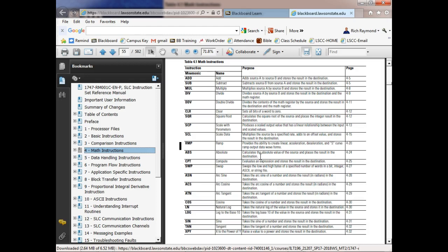And then it's just like robots. So robots, they got tons of instructions they can put into a robot computer, but why would I need the welding instructions that would eat up memory that I'm going to use for my program if my robot's never going to weld? So that's one of the things when you buy a robot, you need to specify what the application is, and then when they give it to you, it would have the instructions that are required. I think we've only got one welding robot over there that's got it in there, and that's the Motoman robot. Of course, the weld shop, they've got a Fanuc robot, and that robot's got all the weld instructions.